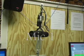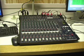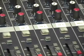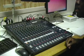These are the microphones we use to broadcast. This is the soundboard we use to broadcast. It's a Yamaha MG166CX USB with a built-in compressor. These are the individual channels. They correspond with various pieces of equipment in the studio. The fader on the channel you're using should be set at 0 decibels. Then you can adjust as necessary.